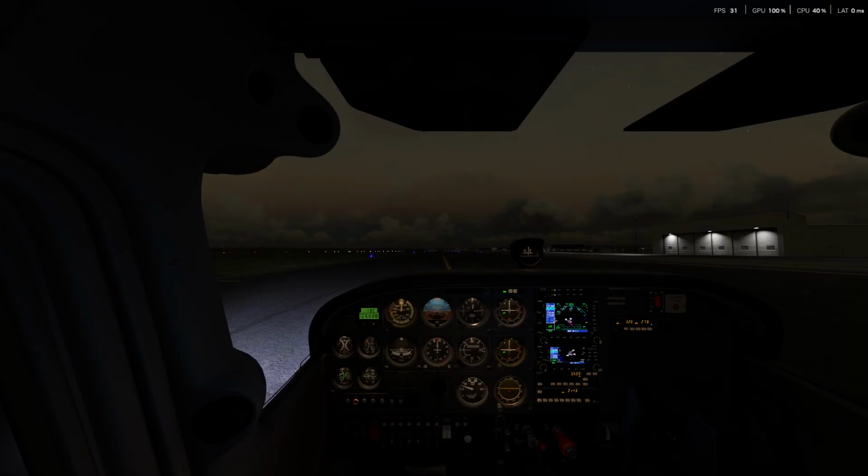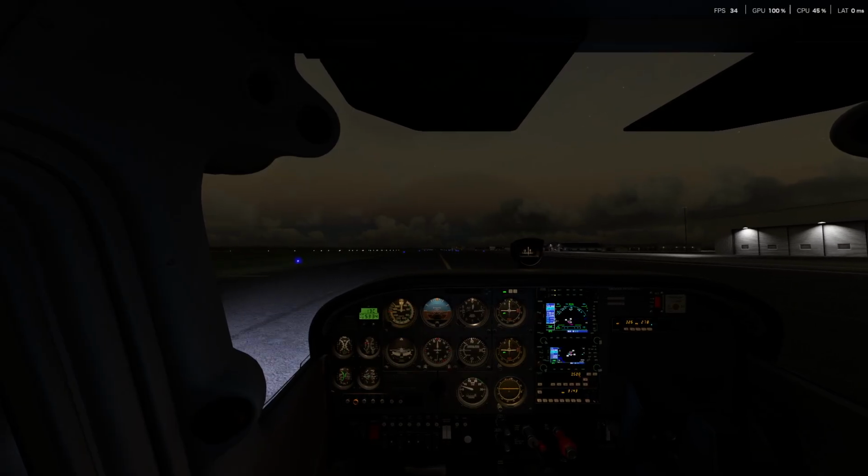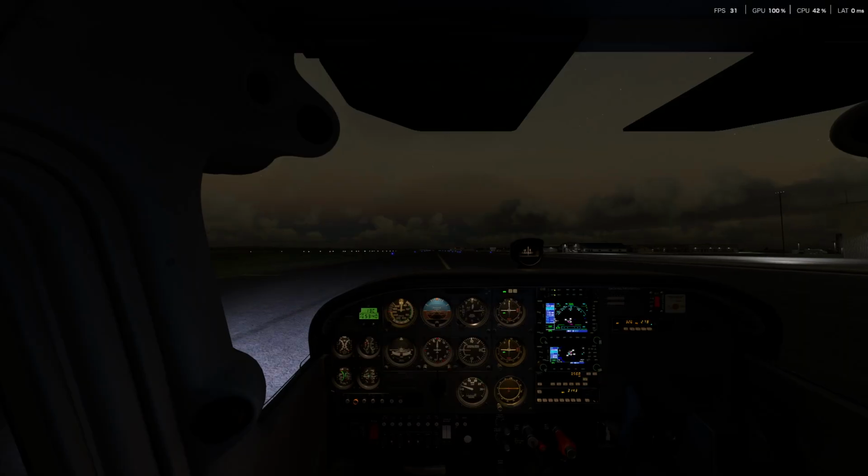Time, we'll record now. Lights as required, the taxi light is on because we're flying a little bit illegally right now. Flaps are retracted, pitot heat is off. After landing checklist is complete. Alright, so we're going to keep taxiing here on Alpha, and then we'll pull into the multi-engine college apron over at apron 2.